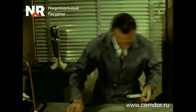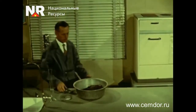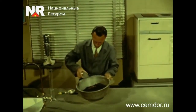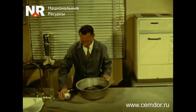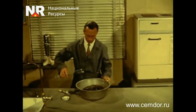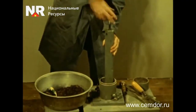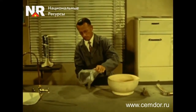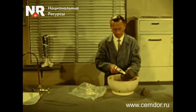After determining the physical and mechanical characteristics of the original soil, it is necessary to assess the effect of various additives and cement on the properties of the stabilized soil. To do this, the soil and a small amount of cement, possibly together with a stabilizer, are mixed, water is added, samples are molded, and they are left for 7 days. After that, the samples are broken up, crushed, and the changes are determined. Characteristics are determined as presented above for each soil composition containing different amounts of cement or additives.